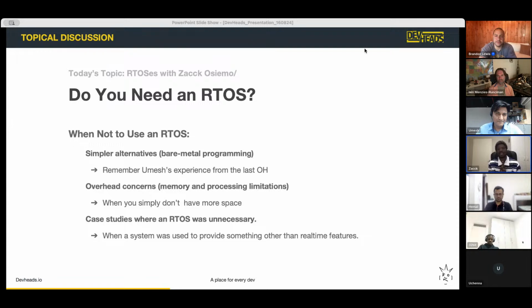Okay, and then sometimes people end up using RTOSs like libraries. Some RTOSs come with HALs, really good HALs, and HALs are attractive to developers because they make everyone's work less. You can do faster, you can depend on open source software, you can depend on good, dependable code. And sometimes you'll end up using an RTOS when you're trying to do something simple, because the simplest way that is documented right now is using an RTOS. So that's usually the wrong time.